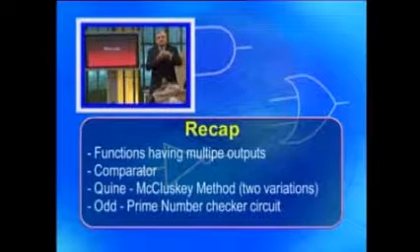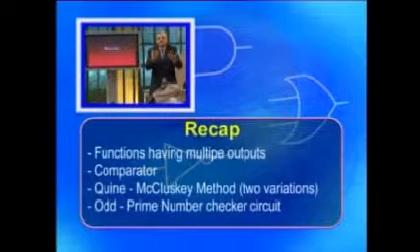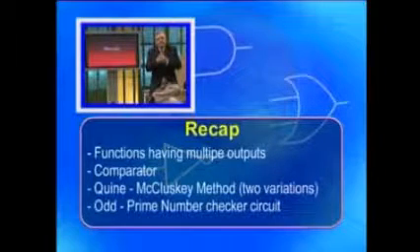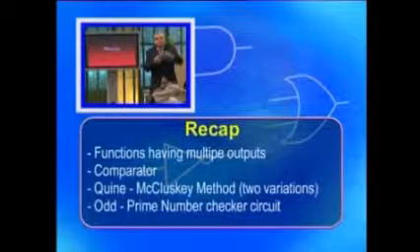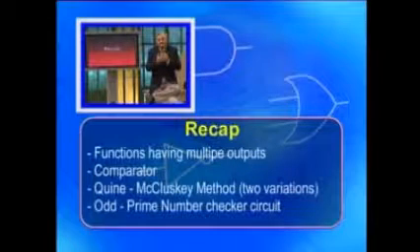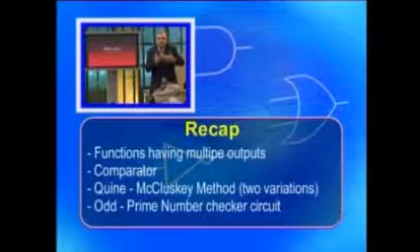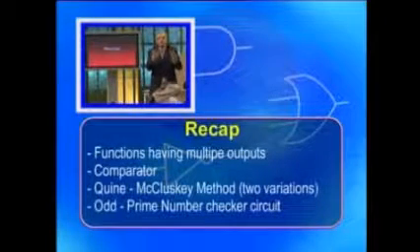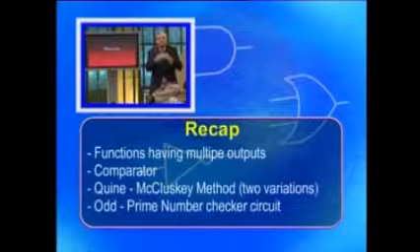Quinn-McCluskey method, we said, is based on a program. Program होगा जिसके through आप solve करेंगे. It is a 2-step method. फर्स्ट स्टेप में क्या करेंगे? बेसिकली यू फाइंड द प्राइम इम्प्लिकेंट्स. प्राइम इम्प्लिकेंट्स कैसे ढूंढते हैं? बेसिकली यू कंपेयर ऑल द टर्म्स एंड यू ट्राई टू रिमूव सिंगल वेरिएबल्स वन एट अ टाइम. व्हेन यू आर अनएबल टू रिमूव एनी वेरिएबल्स, दैट मीन्स यू हैव कंप्लीटेड स्टेप 1.